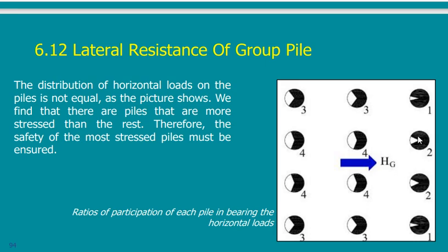affected by this. If these two piles move in front, then this soil is loose now. It cannot carry anything, and similarly all of the amount here of this soil. So if I take this group of piles, then these two piles, they have the number 1, they carry the most of the load. Why?